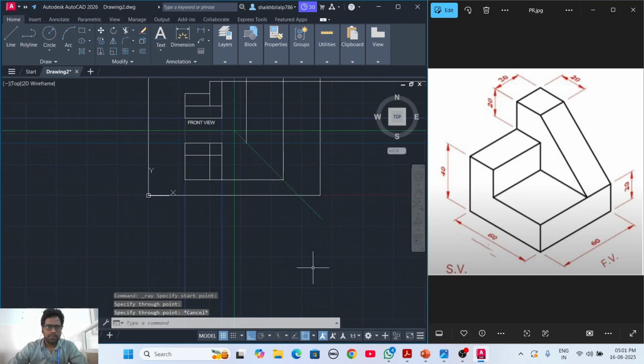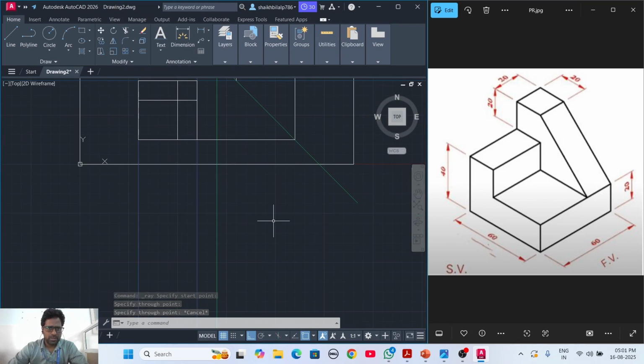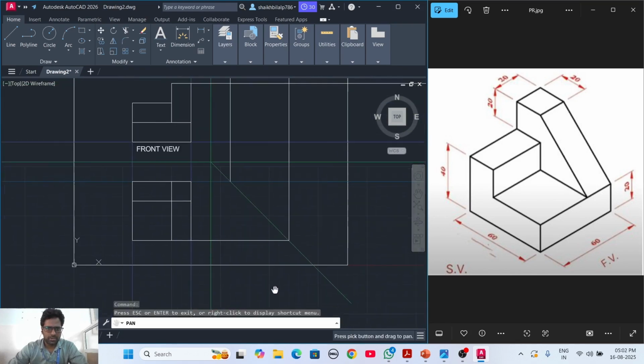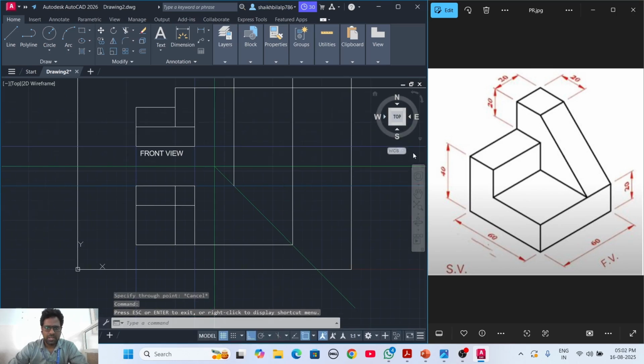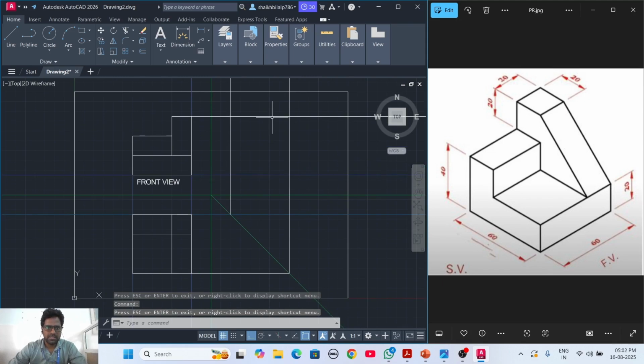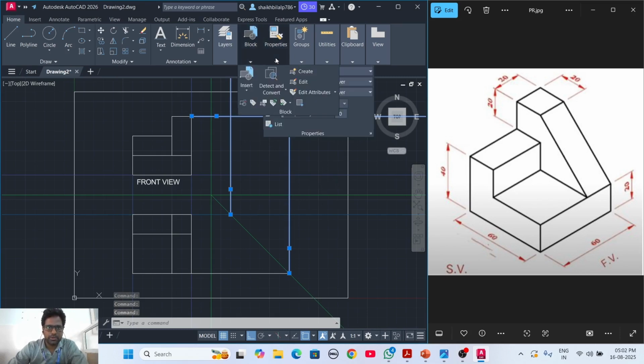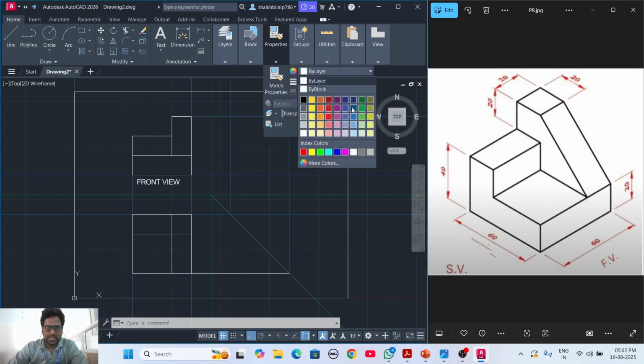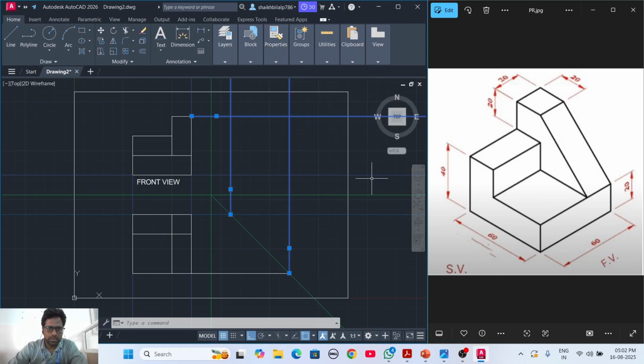So now I have to convert these projection lines into blue. I'm converting these projection lines into the blue color, and then we go for the drawing, and I will trim out the extra lines. So how do we trim out the extra lines? First, I will give them blue color so we can distinguish between the normal lines and projected lines. I have selected these three projections, going to the properties by layers and just putting this blue color, and after clicking, just escape.